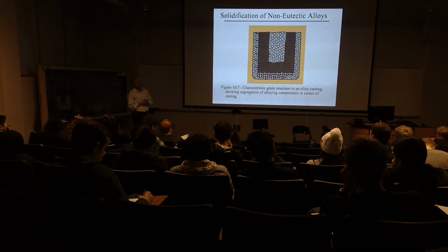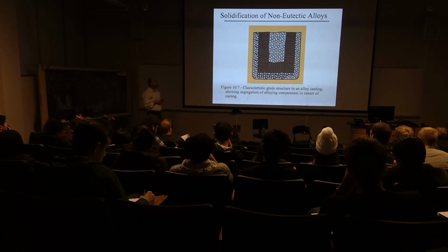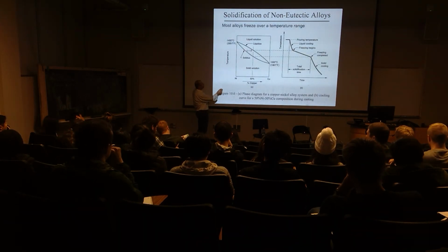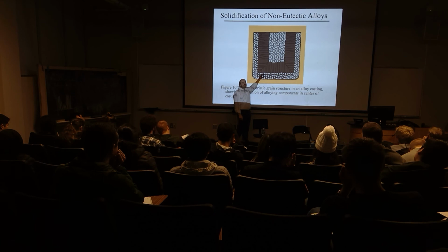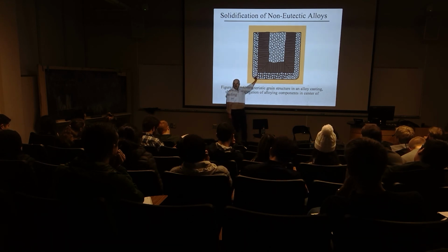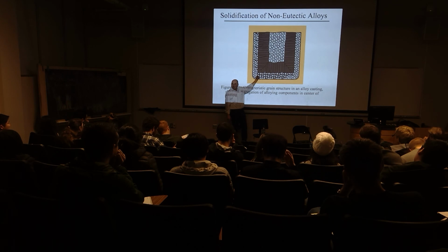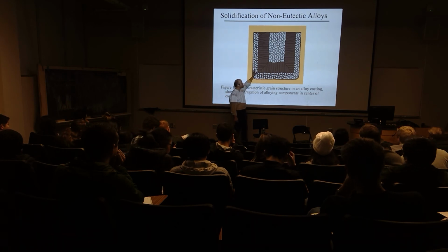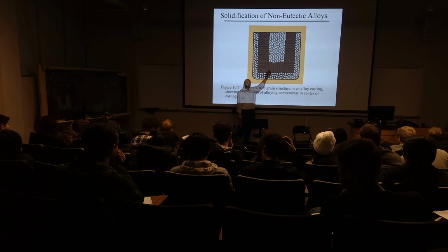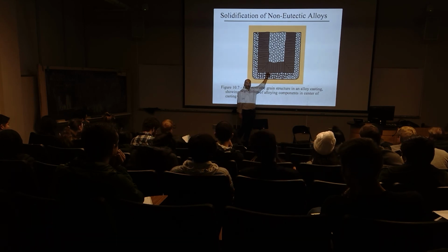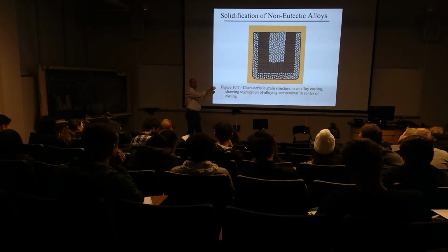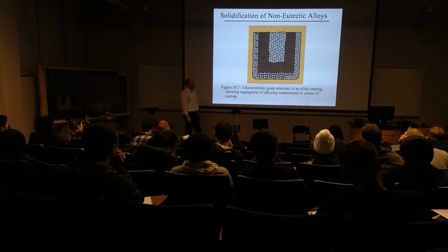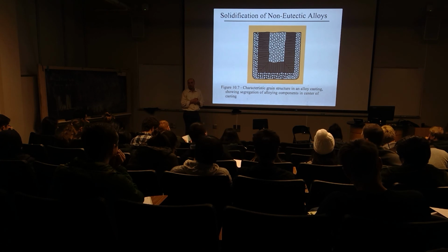So what can happen is we'll get segregated solidification. We'll start to get, of course, the liquidus component that undergoes solidification first. This will be probably uniform solidification, that means of the alloy as defined. Then what's going to go on is, after that initial solidification, we start to get material that has time to solidify preferentially, in which now the material which has the lowest melting temperature will be pushed to the interior of the mold. So your materials now can end up being segregated in chemistry and also segregated in terms of the grain structure.